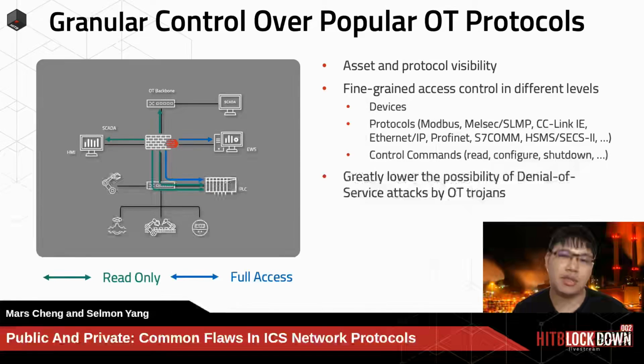recommend intent-based segmentation and implementing technology that gives you granular control to filter and do network whitelisting, to filter the Modbus protocol and other ICS network protocols and control commands, to make sure some things are read-only, some things can follow this, and some things cannot do this. It's very important because most ICS protocols are legacy protocols, so they don't have any security design implemented in the protocol itself. So we need to detect OT protocol attacks at the network level.